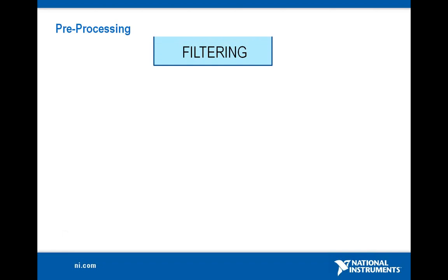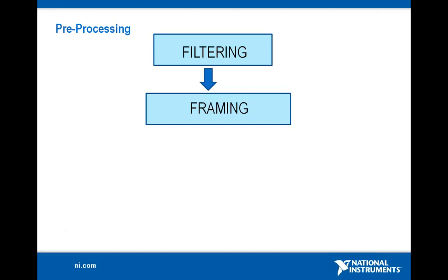In pre-processing, filtering was used to compensate for the suppression of the high frequency part in the voice production mechanism of humans. We use a high pass FIR filter to increase the magnitude of high frequencies with respect to other frequencies, hence improving the signal to noise ratio.